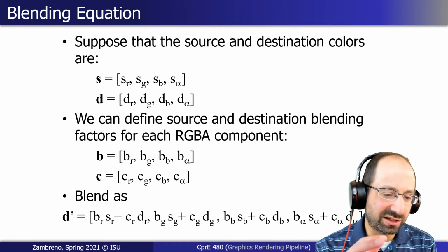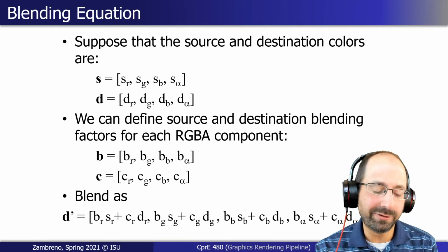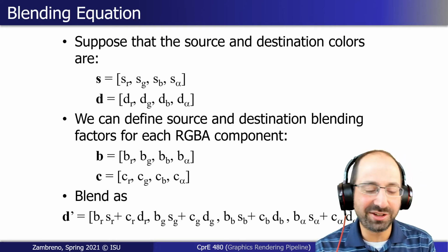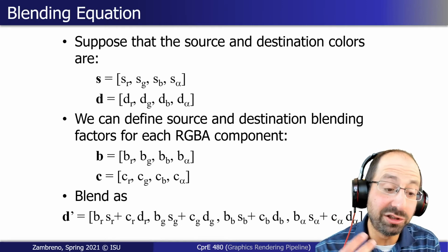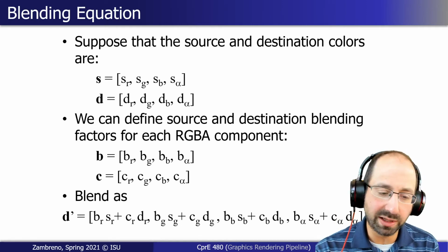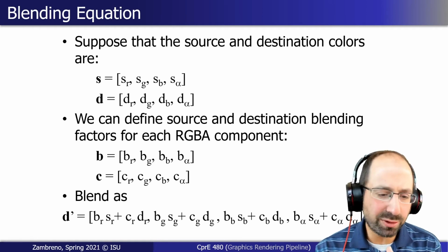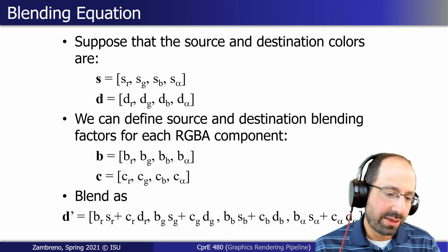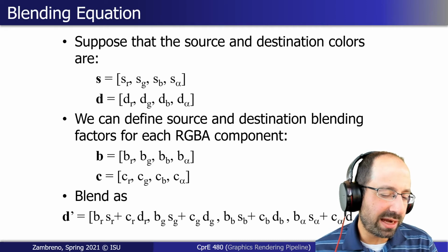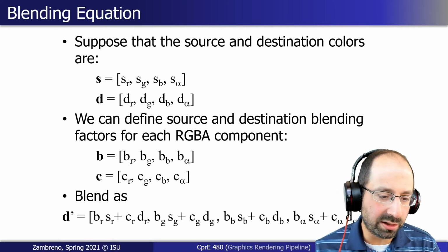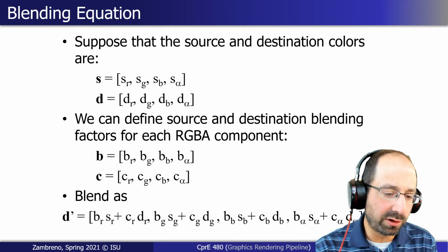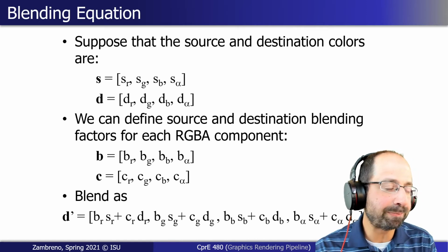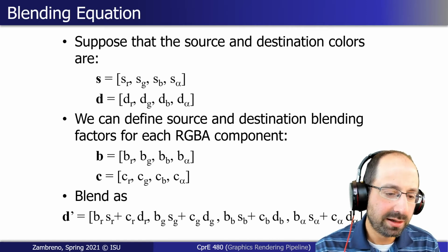Then you can actually start to truncate a little bit earlier and save a 4-bit carry look ahead adder and things like that. If you want to do that kind of micro optimization, we generally don't, but it's possible because ultimately we're dropping it. And I think we can do the same exact thing for the alpha. There's no reason to say for certain that an 8-bit alpha is sufficient for 8-bit color in the other channels, because it does kind of multiply. Eventually, you will underflow your alpha information, but I think it's okay.